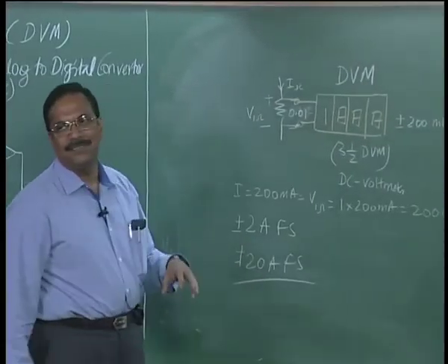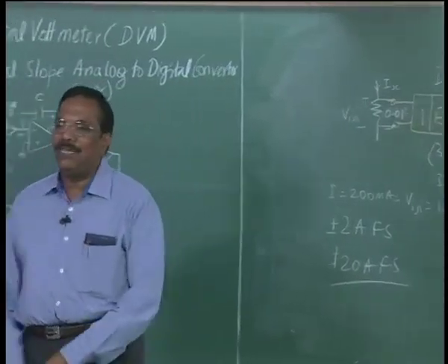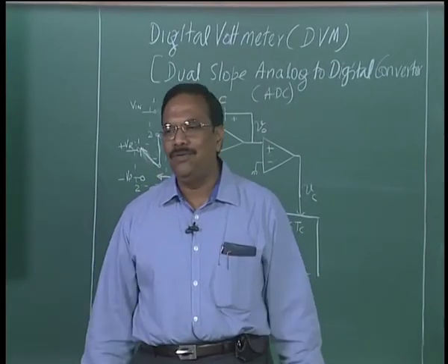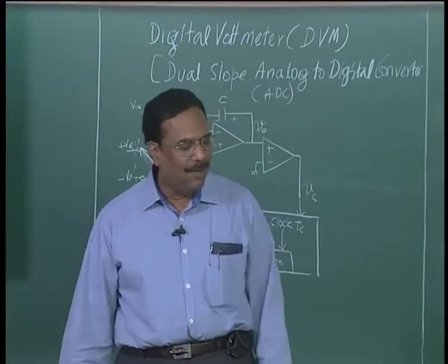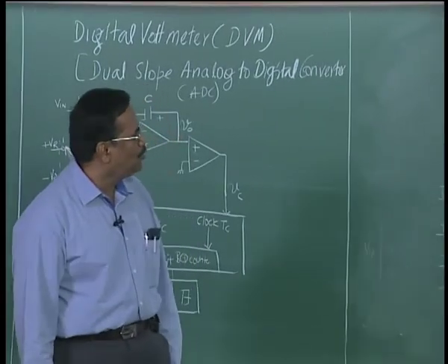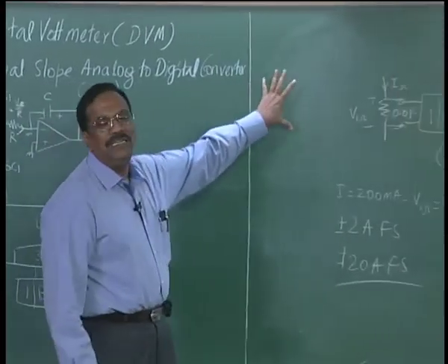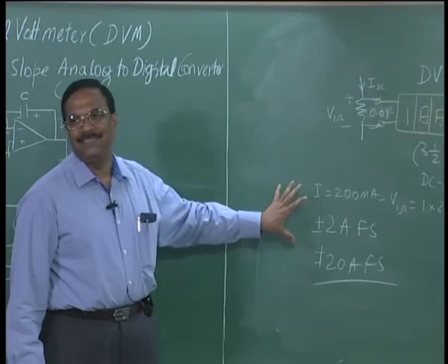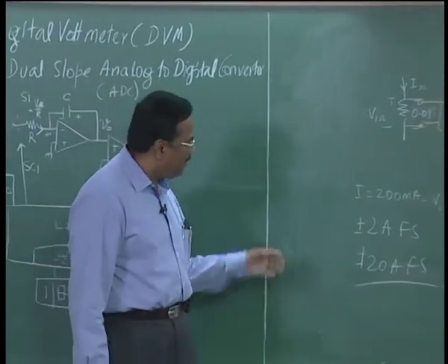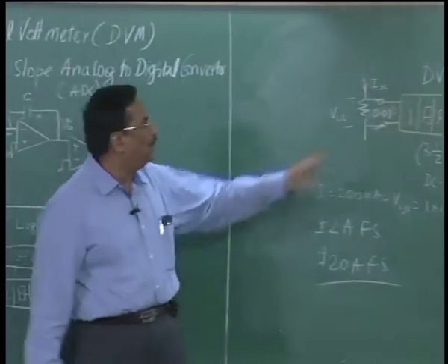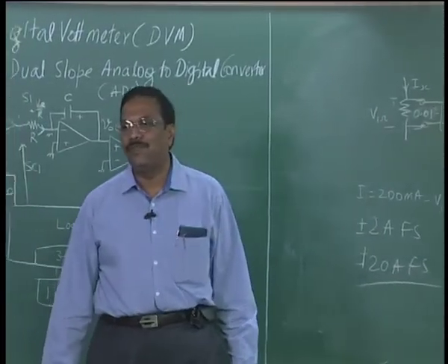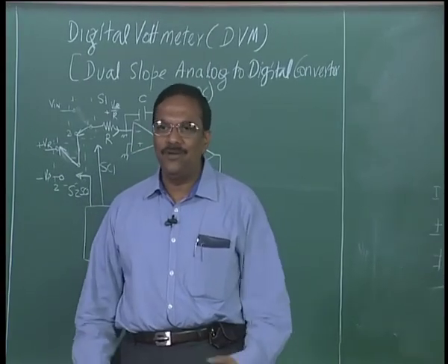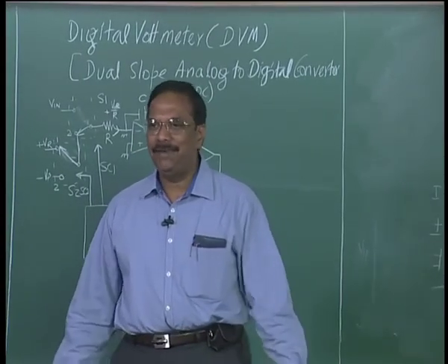in the shunt resistor. So by connecting a potential divider we can convert the basic 200 millivolts or 2 volts full scale digital voltmeter into digital voltmeters of higher value as well as digital ammeter, right. So I can put a 10 ohm here, then what will happen to my full scale current? It will become 20 milliamperes. If I put 100 ohms, it will become 2 milliamperes, right.